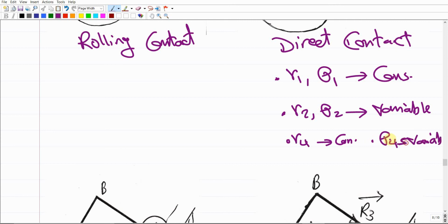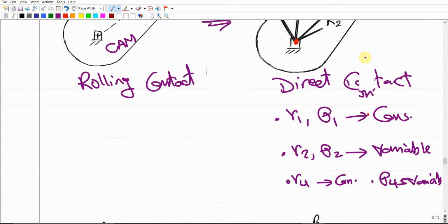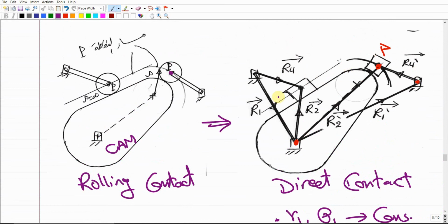So that's why we're gonna end up here with a Coriolis acceleration if we treated this one. The same thing applies to the other one. Here, the slider is going to slide. This is typically the same like a link, and there is a slider that slides over a surface, but this surface is a movable surface, right?